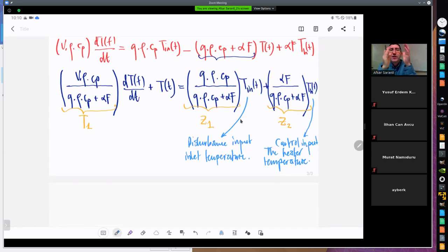That means even if you apply the same input, but you apply it with a certain time delay, the output will be different. With a time invariant system, it doesn't matter when you apply the input, the output will just be a shifted version of the same output that you had before moving or shifting the input. Okay, are there any questions at this point?